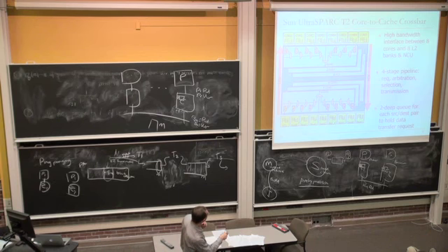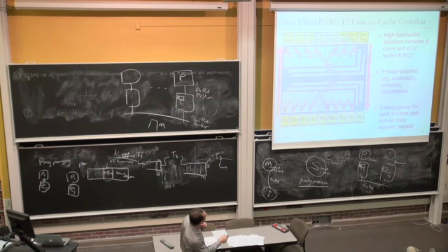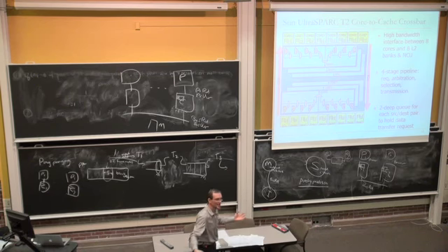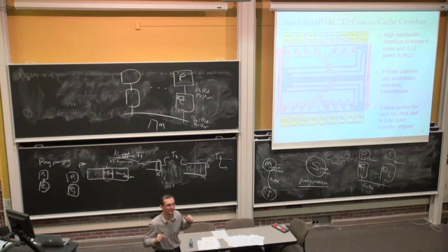And when the cache needs to respond, again, a similar arbitration happens. If, let's say, core 0 requested from both bank 0 and bank 5, then both banks need to send the packet, send the data back to core 0. They need to arbitrate, right? So that's where a network like a Crossbar is useful. In this case, they have 8 cores and 8 cache banks, so it's not that many, right? Even then, this does consume power.